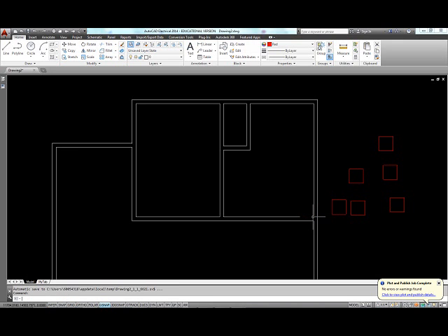Oh, that was not correct, so Control Z. One more time, move this object, spacebar from this end at, I need to go to the X direction first, 100 comma 1140. There it is. Now let's trim using this object as cutting edge, spacebar, and then choose that line.